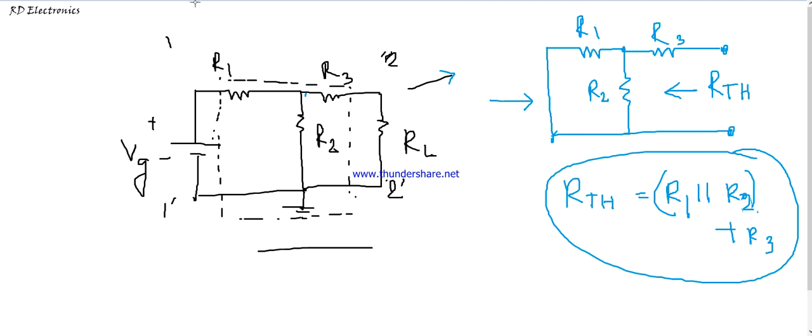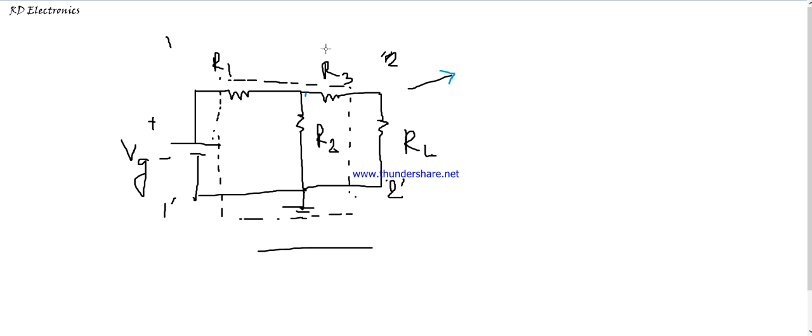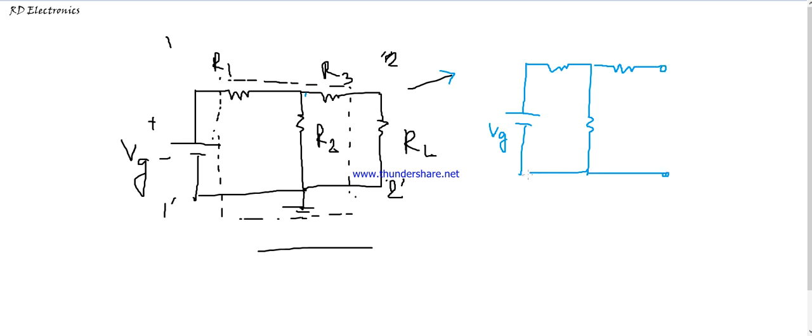So now we calculate the Thevenin voltage. So what are we going to do? At first, in the presence of this DC voltage source, draw this circuit again and just open circuit the load terminal. Here are the three resistances R1, R2 and R3, and we measure the open circuit voltage from here.